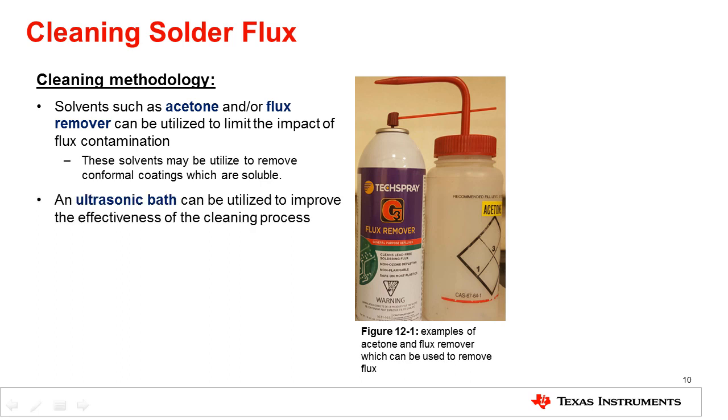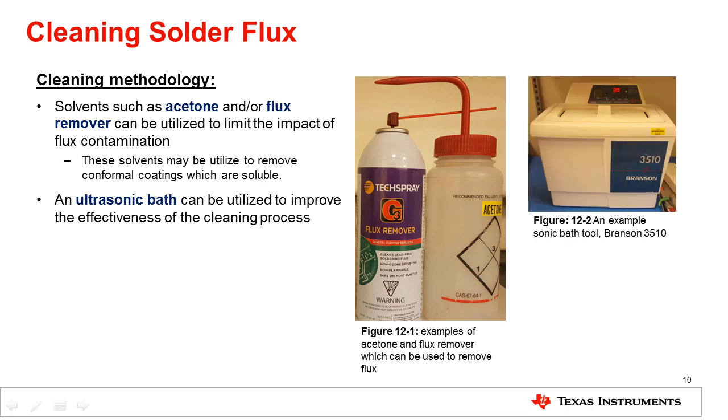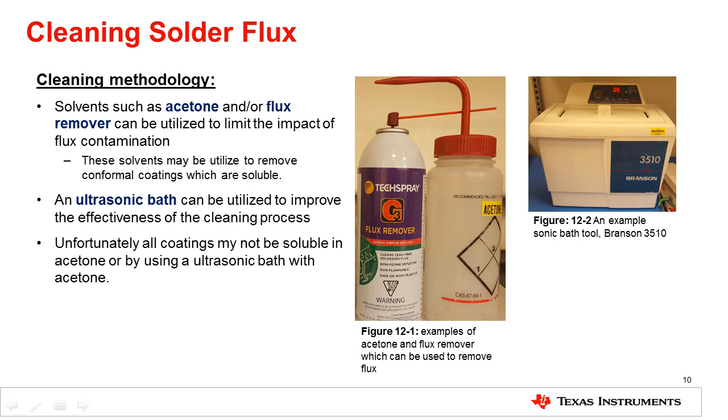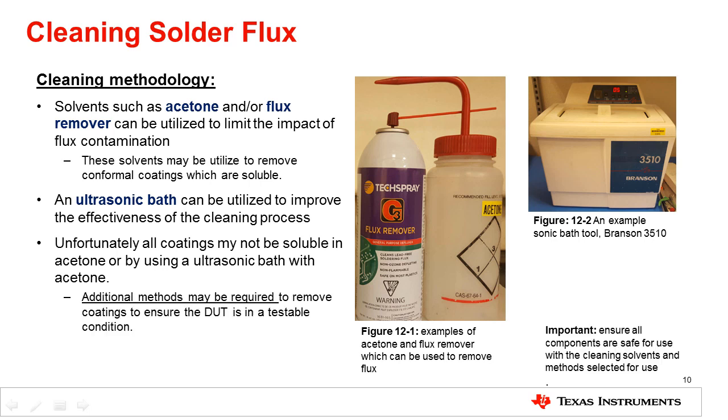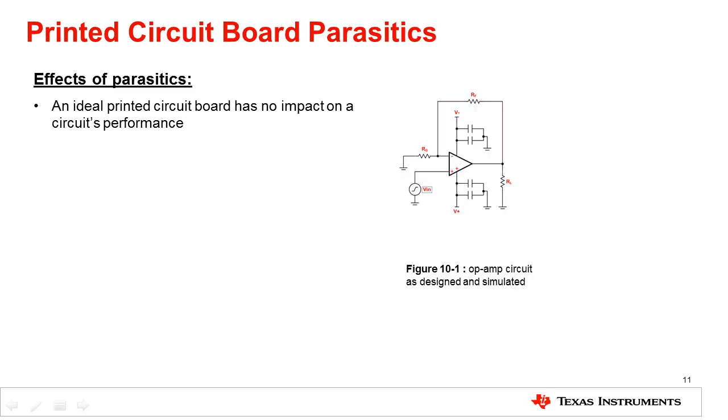To improve the overall effectiveness of PCB cleaning, an ultrasonic bath can be utilized. An example of a tool used in prototyping environments is the Branson 3510. Lastly, all coatings may not be soluble in acetone or by using an ultrasonic bath with acetone. Therefore, additional methods may be required to remove coatings to ensure the DUT is in a testable condition. Please refer to the flux supplier's technical documents for details.